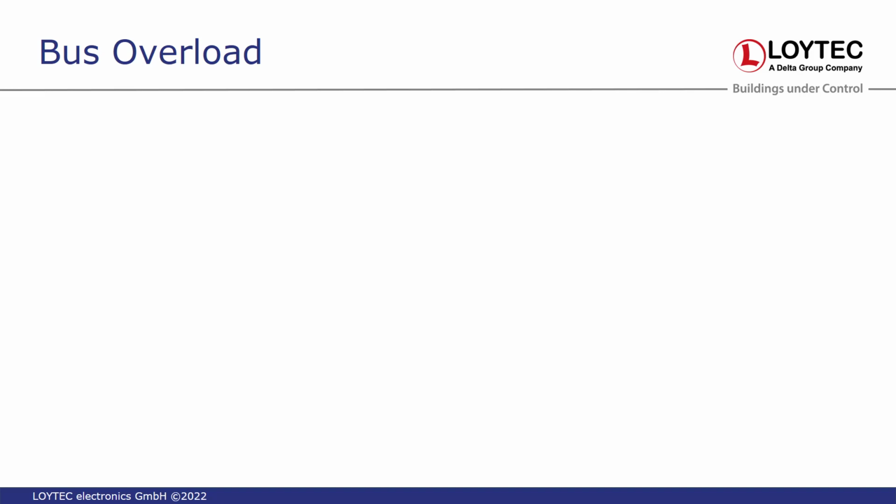But the second thing is how many logical addresses you have available, so how many lamps you can address. That's a logical thing, how many short addresses you can assign. And here the limit is 64. So when you put more ballasts on the channel, you will have two issues.